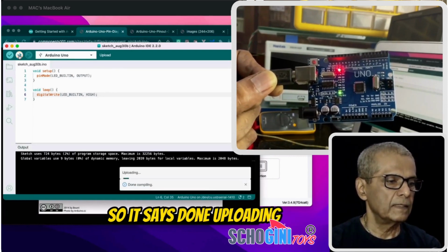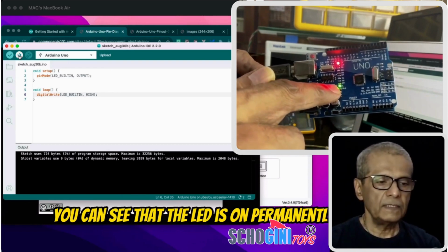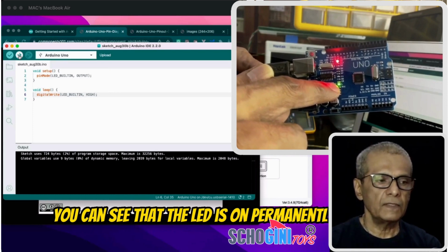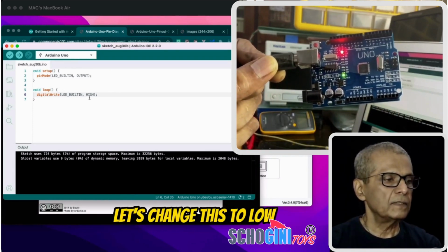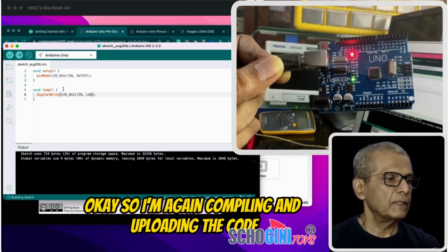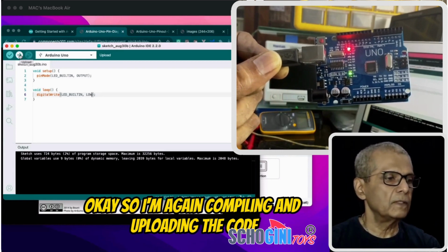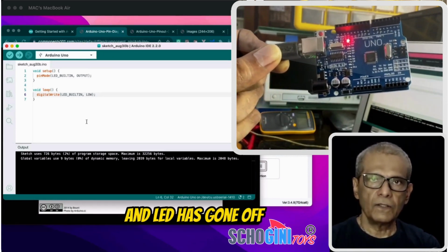So it's saying done uploading. Now do you see this? You can see that the LED is on permanently. Let's change this to low. Okay, so I'm again compiling and uploading the code. It's saying done uploading, and the LED has gone off.